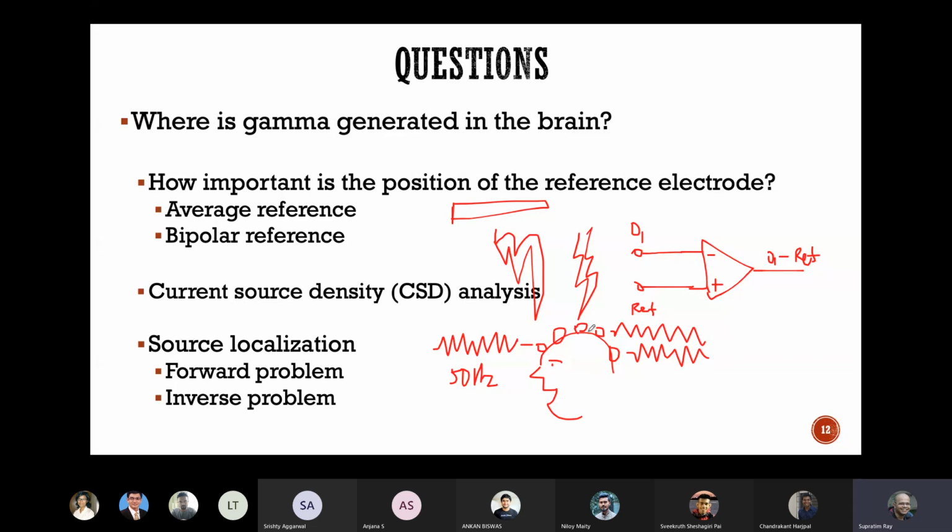So it's essentially some charge developing on the surface, which is getting picked up by the electrode. So a good strategy is to have one electrode which is connected to the earth, the ground, and it basically just takes all this charge that is developing and shunts it to the ground.